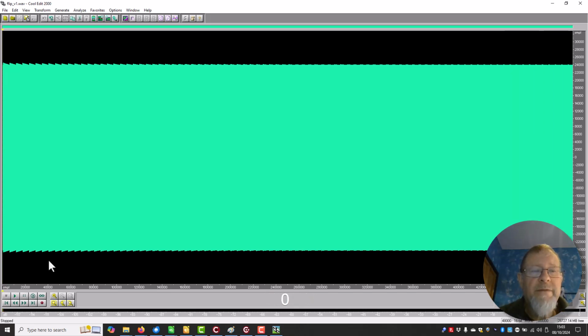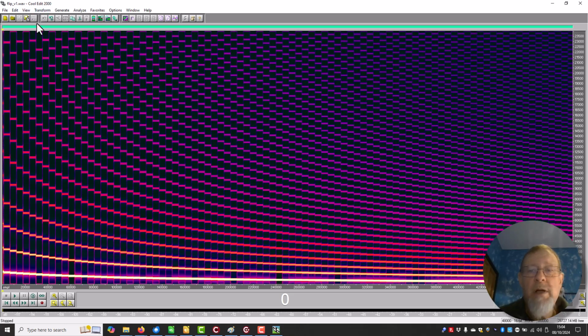And I have swept the frequency using the time constant of the modelled resistor capacitor, and that should be a continuously descending tone, and you can hear it sort of stepping. So all is not well with what we have here. And if we look at the spectrum, oh yes, we can see we're getting all sorts of stuff up to whatever frequency.